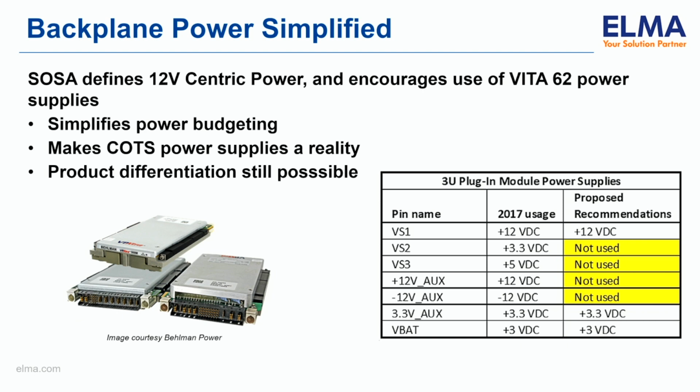Another thing that might not be obvious at first is we've taken some steps within SOSA to define a power definition that again, really encourages integration, really encourages the development of a COTS market for power supply units. Specifically, we collapsed the 3 power planes, 3.3, 5 volt, and 12 volt, just to one. Just 12 volt is the only one used in SOSA plug-in cards.